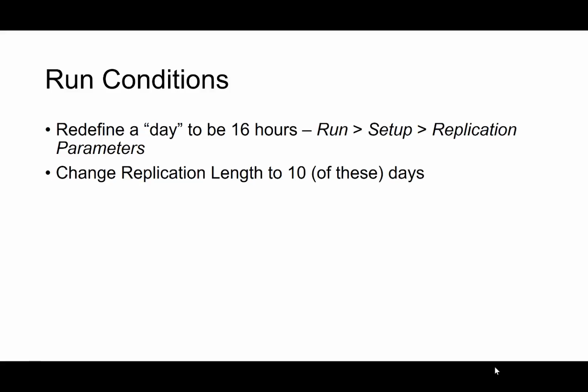So, run conditions. Let's redefine a day to be 16 hours, and you can do that under Run, Setup, and Replication Parameters. And then change the replication length to 10 of these days, because we're going to do 10 days instead of just the one.